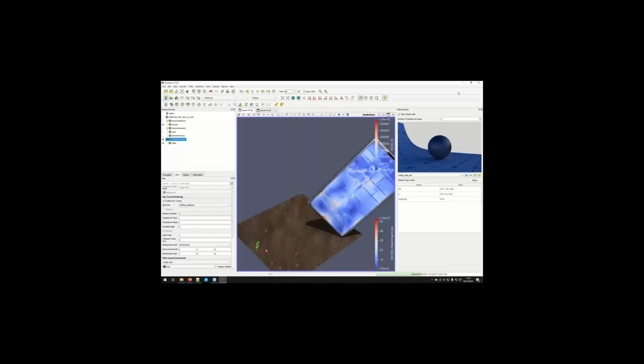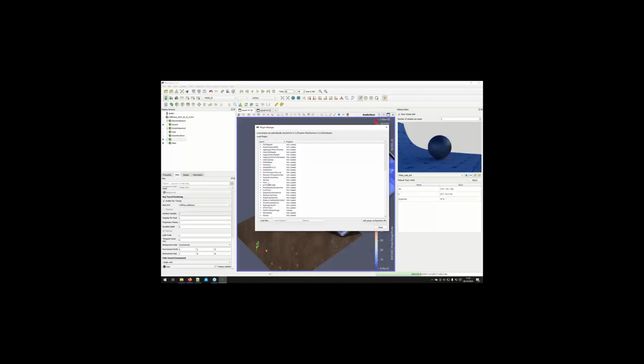And about rendering, I can also mention that in ParaView you have the NVIDIA IndeX technology also available for volume rendering. So in Manage Plugins you have the IndeX plugin. Is it IndeX or NVIDIA? Yeah, PV NVIDIA IndeX. So you can activate this plugin, and you can create a dedicated render view, which delegates rendering to the IndeX library using your NVIDIA GPU and so on.